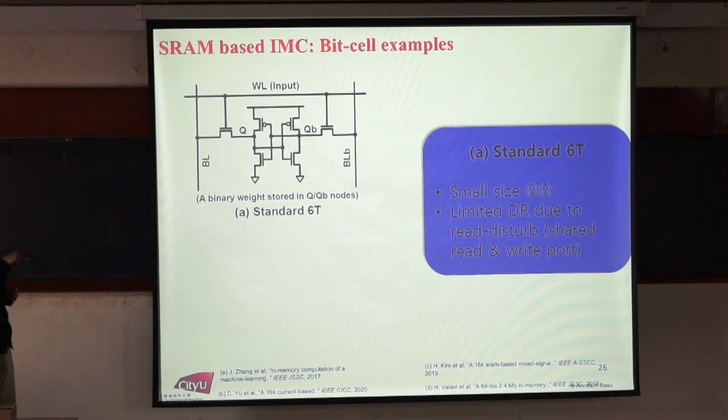So you see in these cells, when we want to read some data from the cell, we also change the voltage on the bit line and bit line bar. Now suppose one of these cells is storing a 0, so then it was discharging. There is some other cell that's storing a 1, which is not discharging. So now think, if the bit line voltage is going down a lot because many cells in this column are discharging, then the cell that was storing a 1 will now see a very low voltage here.